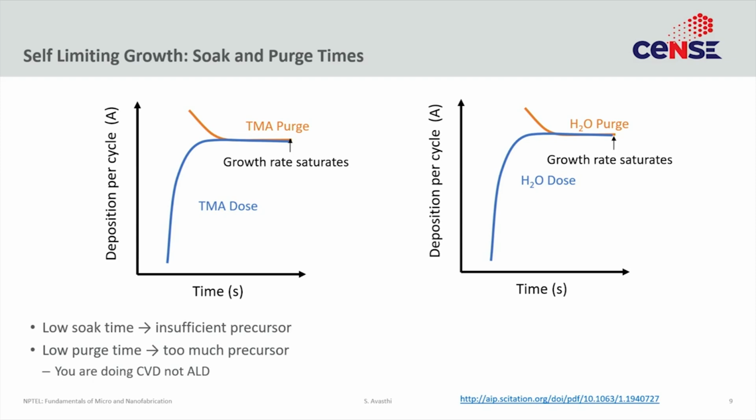So, what you would do is the deposition, plot the growth per cycle of that precursor, and change the dose. You change the dose from some small time to some large time, and you plot the GPC. For very short times you will have incomplete chemisorption, and because of that you will have suboptimal growth rates.